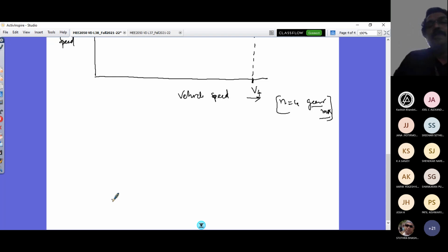Unless I have to go for sudden braking, I will not get my gears to the lowest gear. So there is some rounding off, and the procedure is different. However, trucks are considered heavy vehicles, and the intermediate speed or the operating speed range of your engine is decided based on geometric progression. That I would be considering even now for this vehicle model.